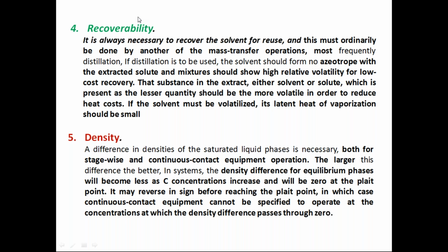Recoverability should be very easy. It is always necessary to recover the solvent for reuse, so the B can be separated and sent back. This must ordinarily be done by another mass transfer operation, most frequently distillation.